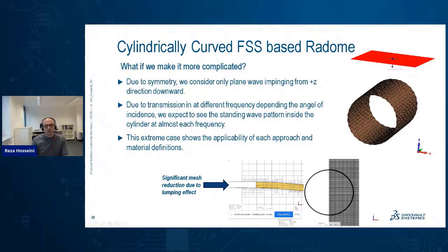Again, here's a screenshot of how the TLM solver and TLM mesh could be a significant help in terms of calculation. You can see here that we're saving lots of mesh inside the cylinder. Basically there's just air, so the geometry is at the edges, and we do a better meshing there.